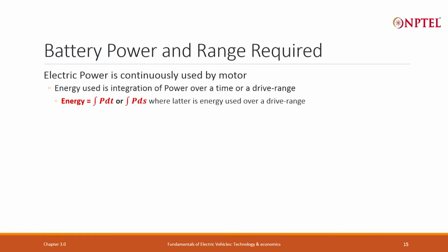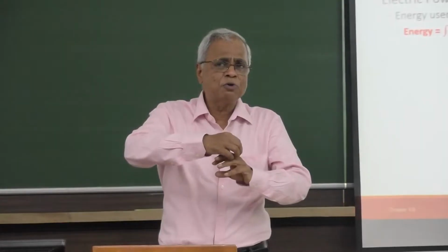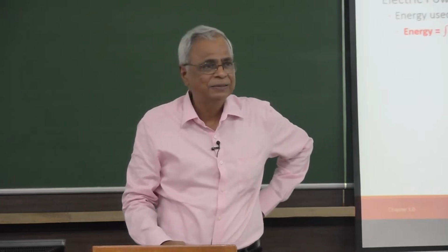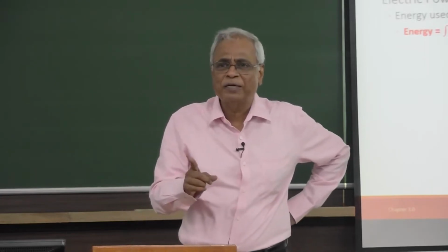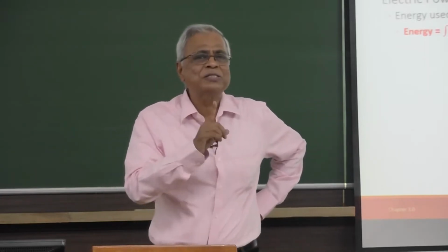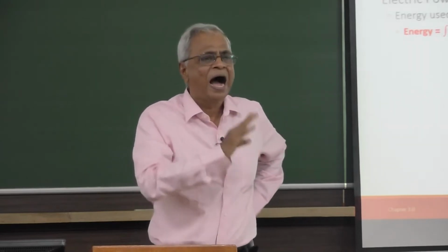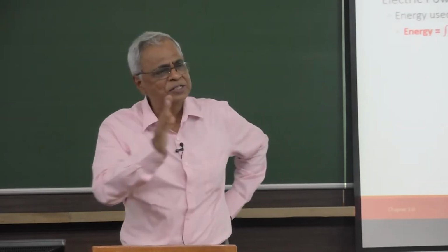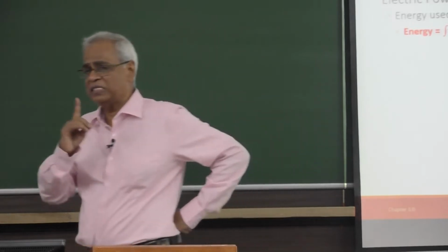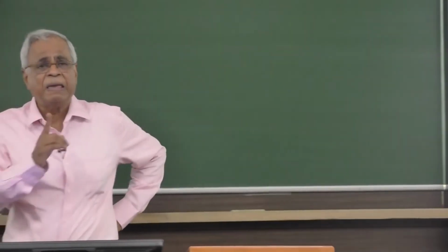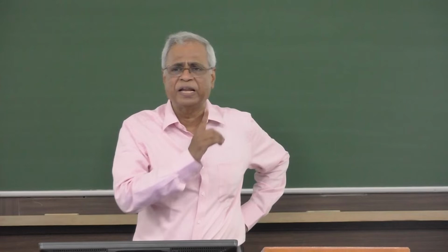because if you tend to draw more power, there may be energy, but if you tend to draw more power from a battery, as we will talk about later on, you are using it at what is called higher C rate, higher charge rate or higher discharge rate. Higher C rate of a battery impacts the battery life negatively.